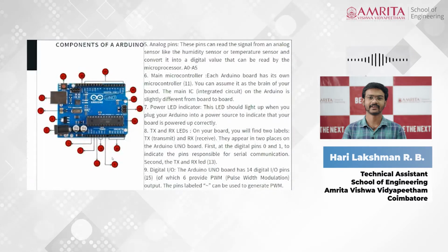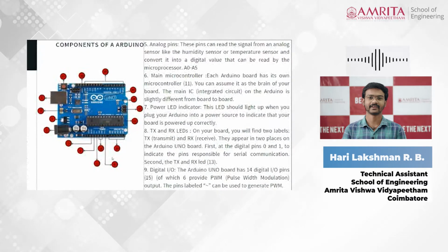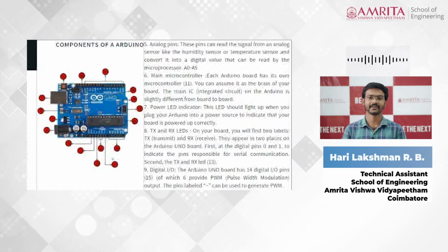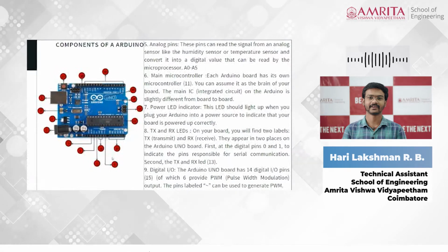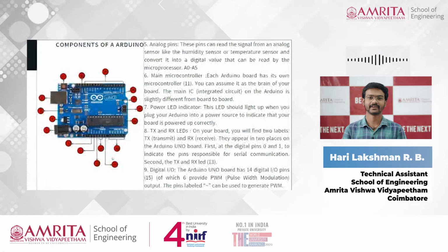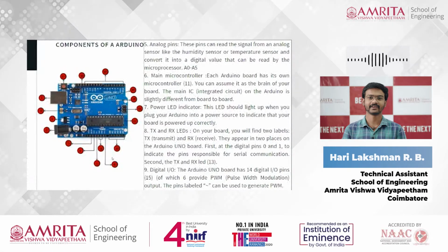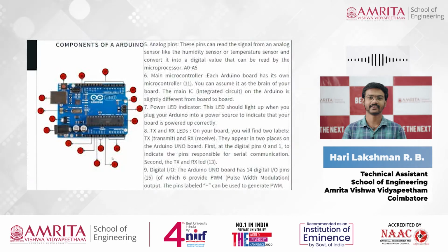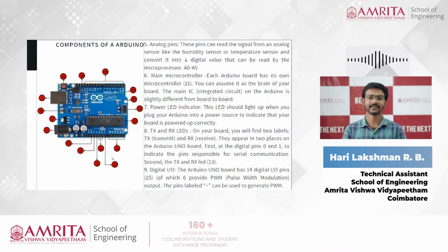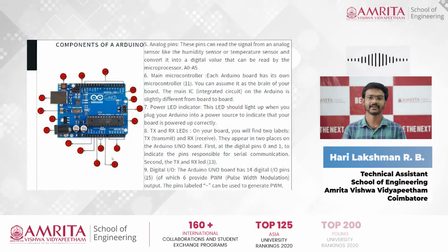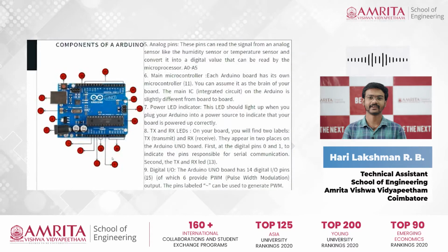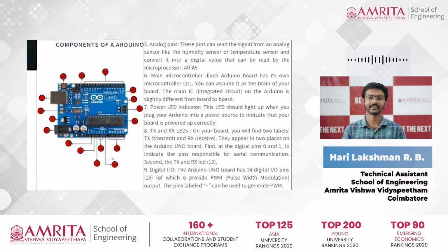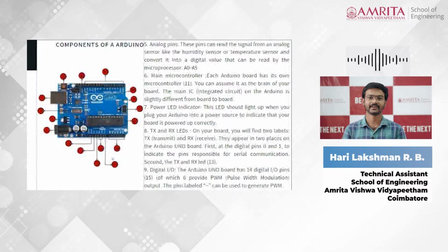As I mentioned in the previous slide, the pulse width modulation outputs vary from board to board. These pins can be configured to work as digital input pins to read the logic values zeros and ones, or as digital output pins to drive different modules like LEDs, relays, and motor drivers. These pins are generally labeled with a tilde, which can be used to generate pulse width modulation.